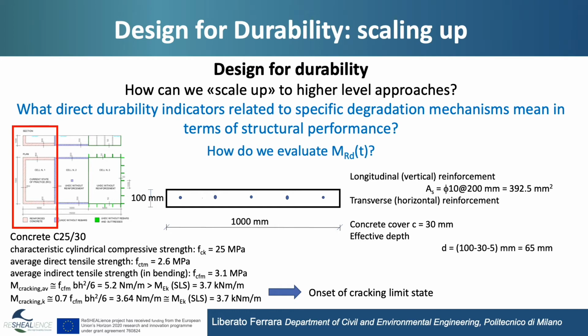The cover depth is 30 millimeters, so we can calculate the effective depth. And also, assuming a concrete C25/30, we calculate the flexural tensile strength, so we can calculate the cracking moment, average, and characteristic. This represents the onset of cracking at the serviceability limit state.